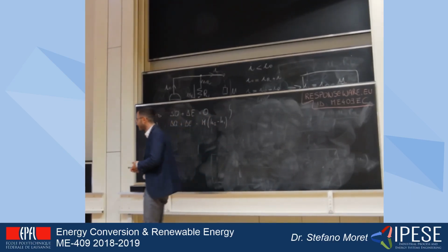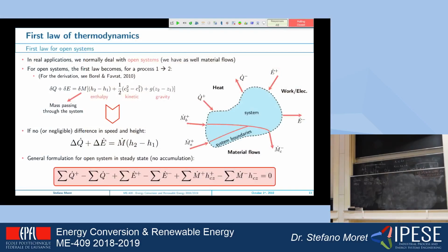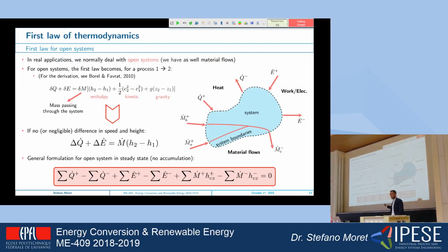principle of thermodynamics. And in practice, when you look at the system, and you'll see in all your exercises, there are some difficult formulas and formulations, but at the end of the day, the general formulation that you should remember for the open system is that if you have no accumulation of internal energy in the system, everything that enters also has to leave. As I told you before, you can really think of the first principle of thermodynamics as the bathtub of water, which, if you don't have any variation in the water level, then everything that enters has to leave.